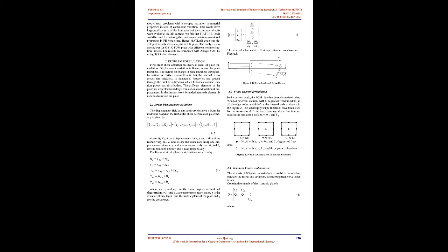[3] carried out the free vibration analysis of functionally graded plates. The variations of the volume fractions through the thickness are assumed to follow a power law function. The Reissner-Mindlin first-order shear deformation theory, which is very appropriate for thick plates, was taken to analyze the behavior of the plate subjected to free and forced vibration.